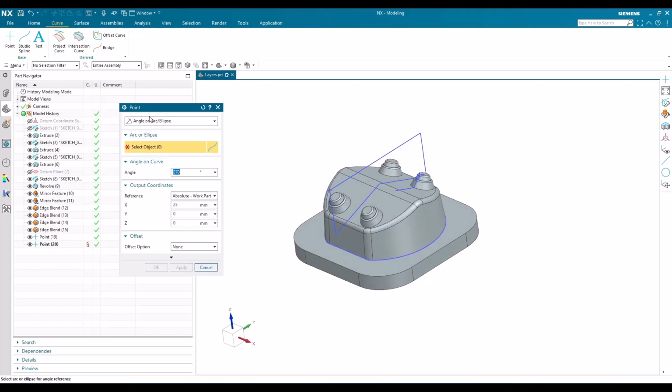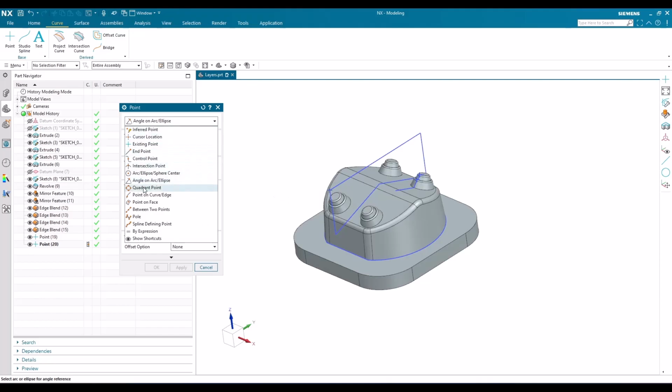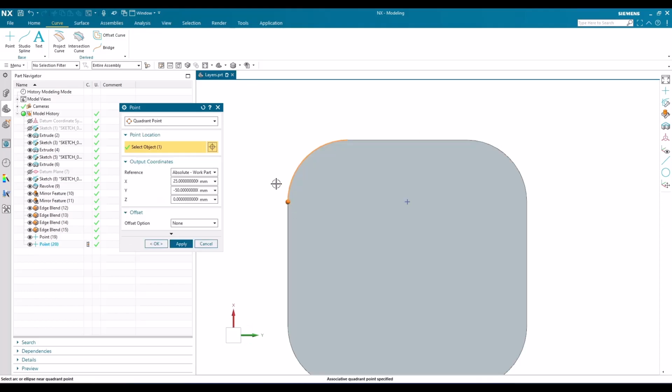So now let us go to the next option. This is quadrant. So similarly, control point, here also quadrant point. For quadrant points, you can say there is a clock, and 12 o'clock, 3 o'clock, 6 o'clock, and 9 o'clock, you can call them quadrant points. So if you draw a horizontal line and a vertical line, where the lines intersect with a circle, that is going to be a quadrant point.